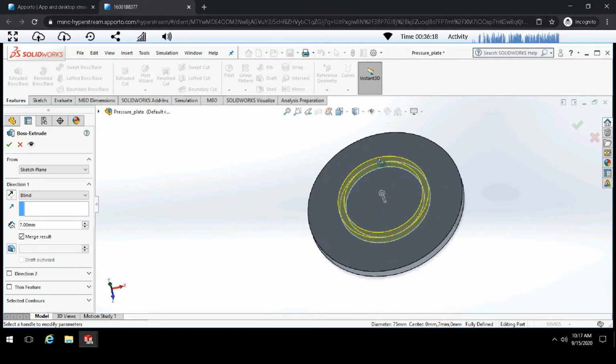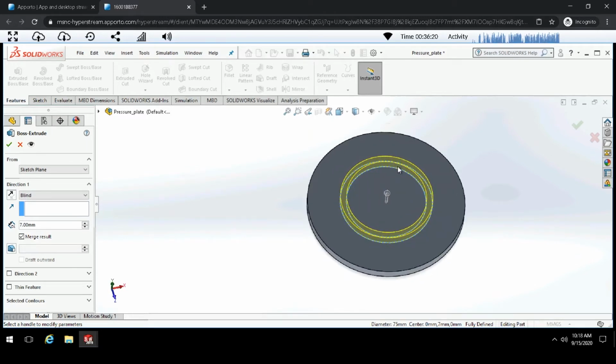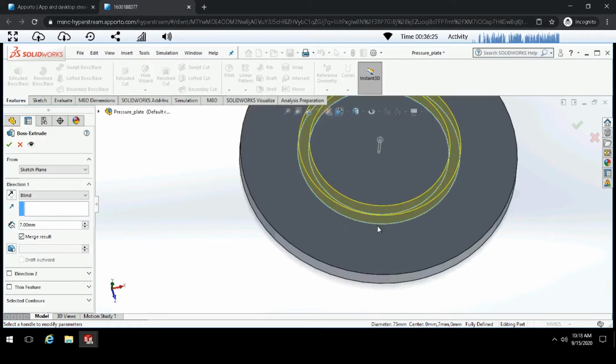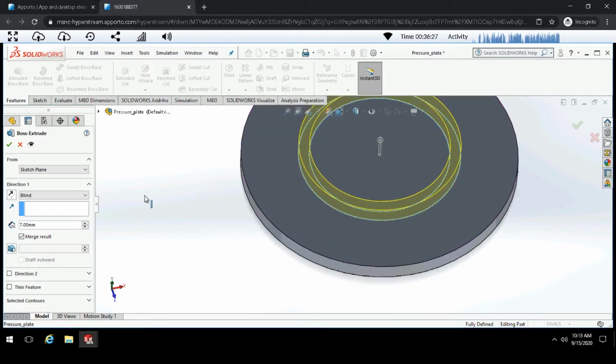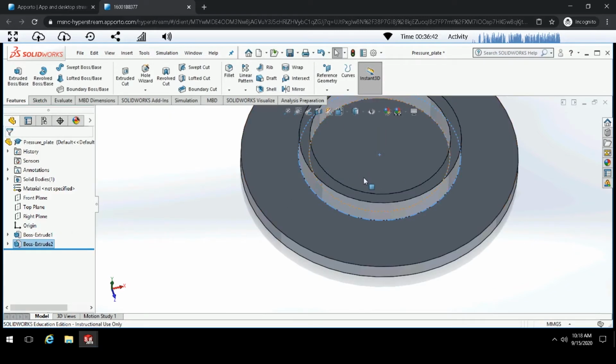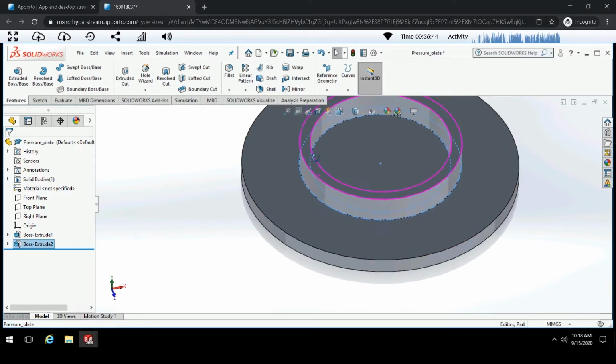If you can shift your view around a little bit, it should look kind of like a cylinder. So then we'll change this to be 12 millimeters in height. So enter 12 in your box here and hit enter a few times until it appears like this.